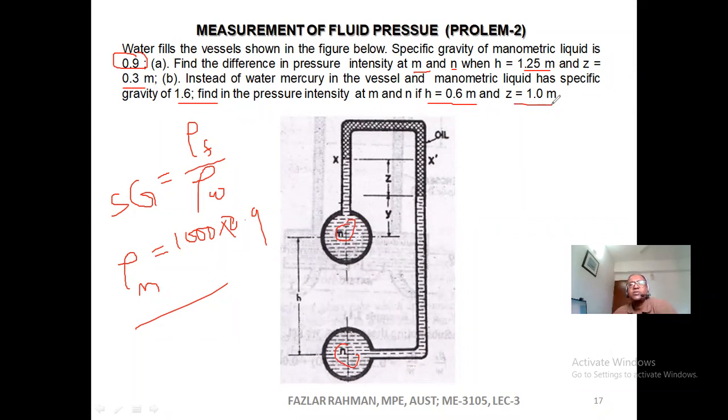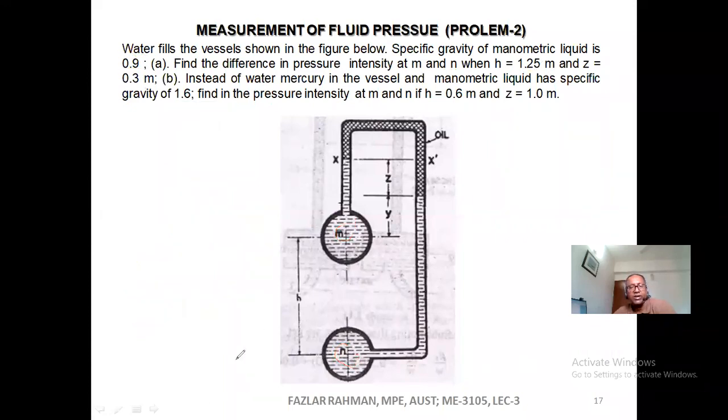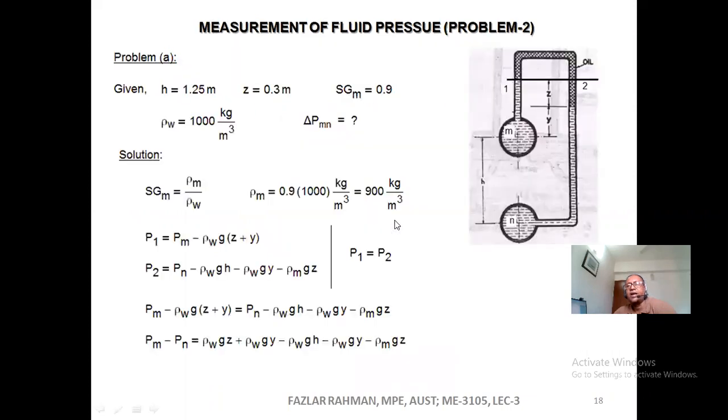So ultimately, just two problems with different situations. Okay, so let's see, very easy. If you just write down the manometric equation, then you can solve it easily. So let's figure out where you can draw the line. You can solve this problem in different ways. Number one, you can draw a line right over here, both fluids in the same line, right?